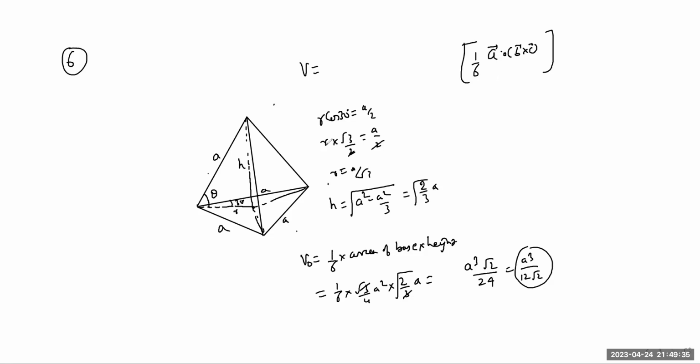So now the bottom is at a depth of h. So what is the pressure here? Rho g h. Not this, this H is different. Don't get confused. So the pressure is rho g h. What is the area? So rho g h into root 3 by 4 A squared. Right? This is the force upward. What is the downward force, which we don't know? Let's call it F down. And the difference of up and down is called buoyancy, which is V rho g.